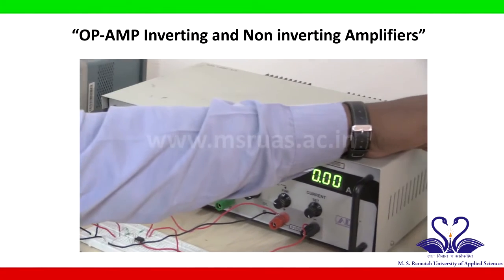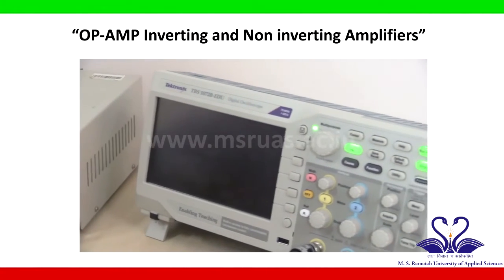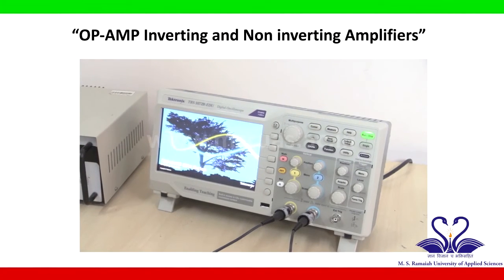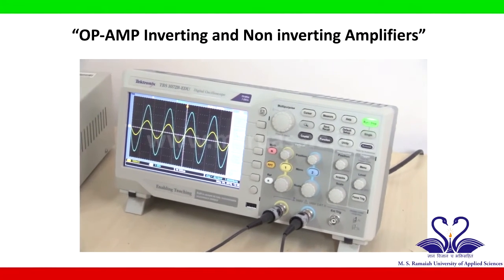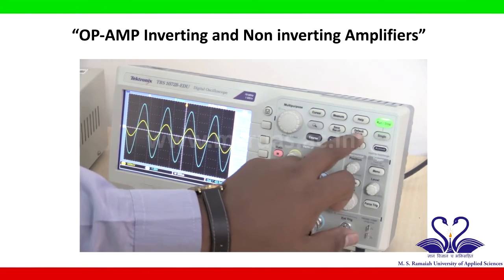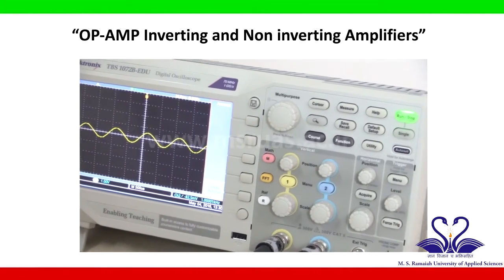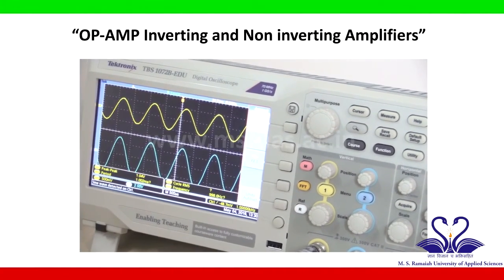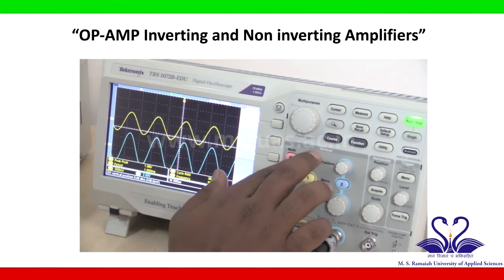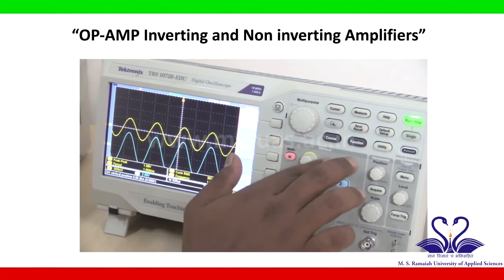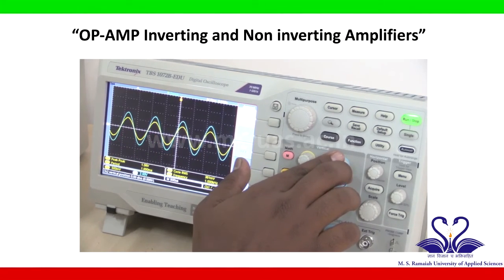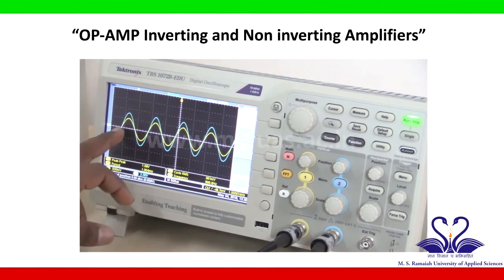Now turn on the digital oscilloscope. So just go to default setup, then auto set. Now we are getting two waveforms. Channel 1 is the input waveform. Just merge these two. Channel 2 is the output waveform, and bring it to the reference line. If you see the input and output waveforms, both are in the same phase, but the output is more than the input.